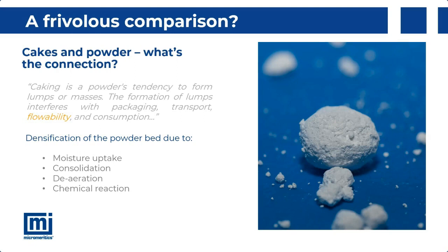Traditional forms of powder flow measurement are unable to investigate this question, as they are unable to sample the powder at differing points within the powder bed. By contrast, powder rheology offers the facility to subsample the powder bed and provide an in-situ understanding of caking behaviours.